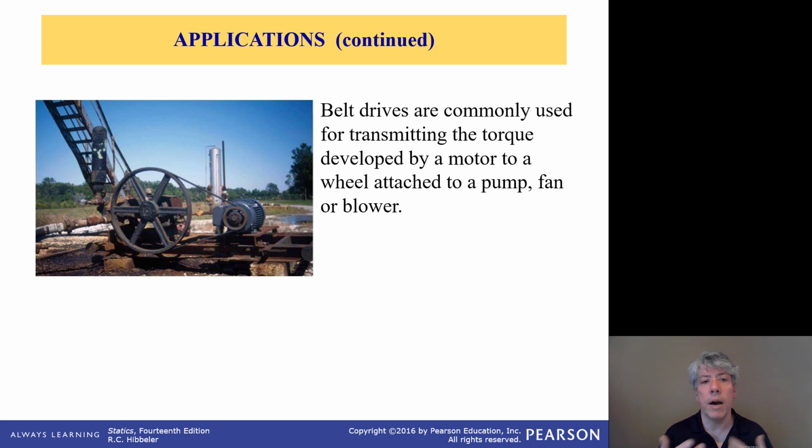And so how do we deal with it? How could it be that there is a difference in tension between these two? Well, we'll see that, but it's absolutely necessary in order to provide a torque to transmit power through to the machine and keep it rotating, say, at a constant speed. Statics can be used for analyzing that situation because the output wheel and the motor and all this are turning at a constant speed. There's no acceleration once we get up to speed, of course.